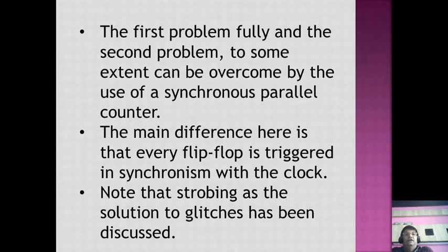Next, the first problem fully and the second problem to some extent can be overcome by the use of a synchronous or parallel counter. That means both these problems can be addressed: the speed of operation is increased in a synchronous counter, and glitch problems can be eliminated. Hence, we prefer the synchronous counter.